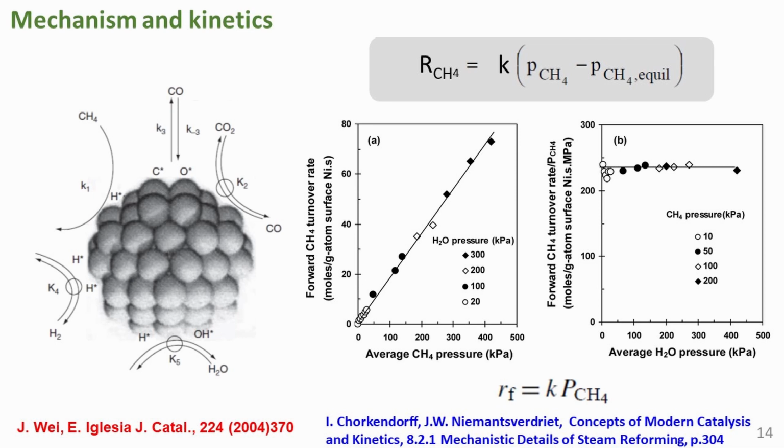Methane is a stable and highly symmetric molecule. It is activated in a direct dissociative adsorption step, which is associated with a substantial energy and entropy barrier. Various approaches have been applied to establish intrinsic kinetics of steam reforming of hydrocarbons. The first kinetic study of a steam reforming reaction studied the reaction on nickel foil in the 1960s. Early work on the kinetics of steam reforming of methane was based on the assumption that the methane adsorption was